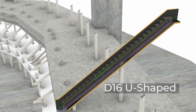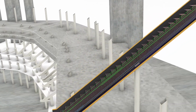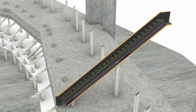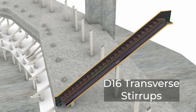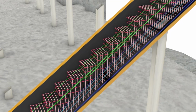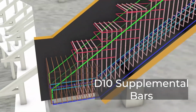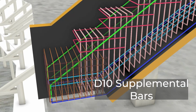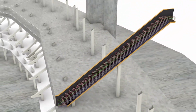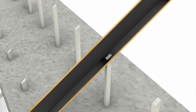Supporting this, D16 U-shaped longitudinal reinforcement is arranged at 200 mm intervals along the main bars to hold them in place and distribute localized stress. D16 transverse stirrups, spaced at 250 mm intervals, resist shear forces and prevent structural deformation. Additionally, D10 supplemental bars are placed at 200 mm intervals at the top and bottom to control cracking and enhance tensile resistance. The rocker beam is precisely connected to the standard column.